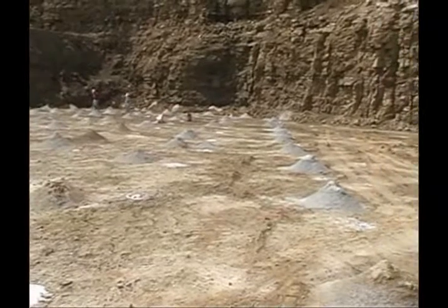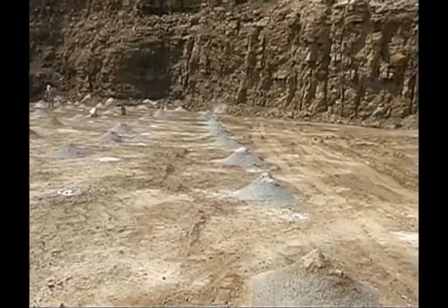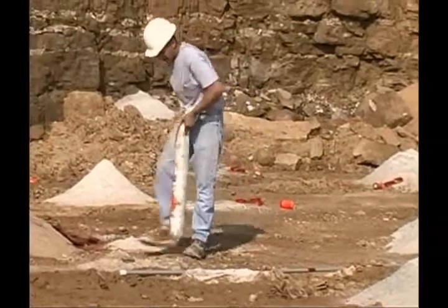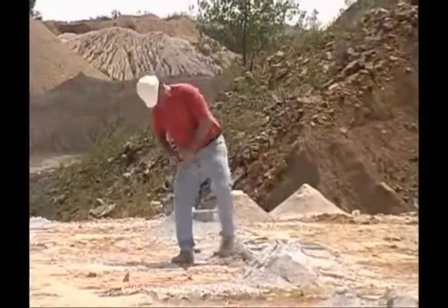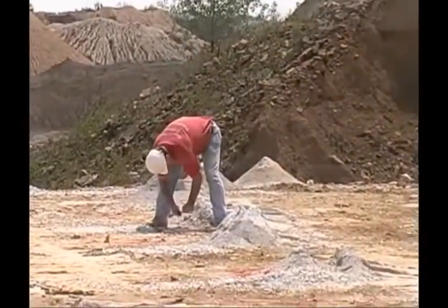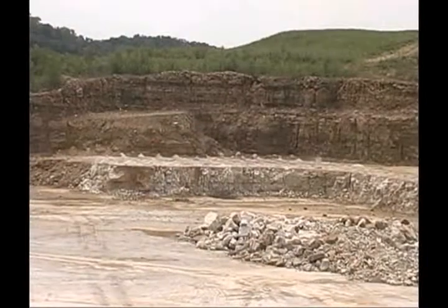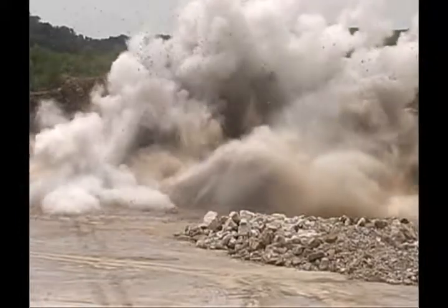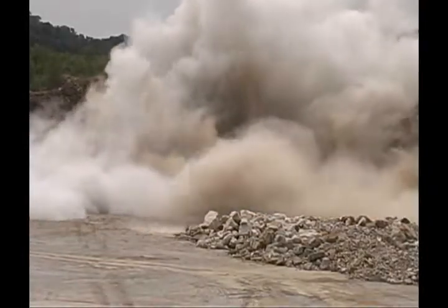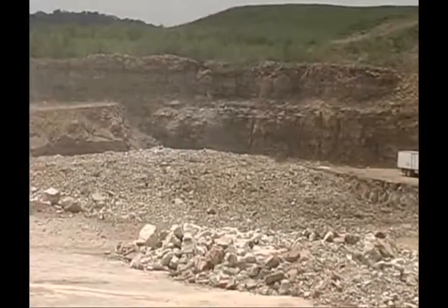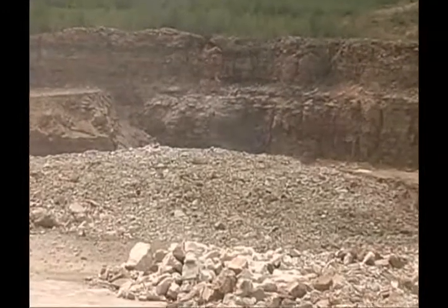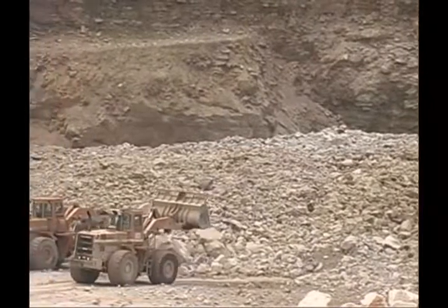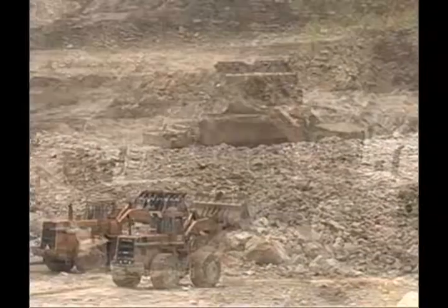The drill pattern and hole location is important to produce a good, workable shot. The drill holes are loaded with dynamite, or sometimes alternative explosive, and wired. The quarry ledge is shot to prepare it for production. The technicians must visually inspect the downed shot for any objectionable material. This material must be removed prior to production.